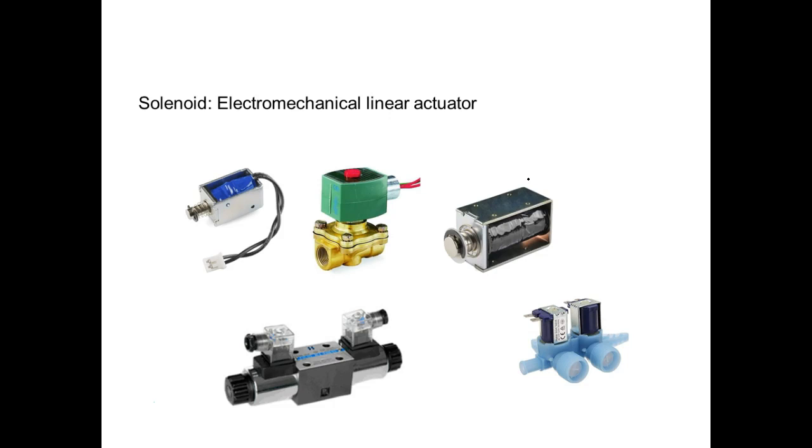If you look in the back of your refrigerator, if you've got an ice maker back there, if you've got water in the door, there are going to be these things back there. These are solenoids. These are valves that control the flow of water. These are what we call directional control valves. These are solenoid operated. So what they do is we shift a vane, we call it a spool, inside a valve to control the flow of fluids. So we can make robots go up or down or stuff like that. They're pretty strong.